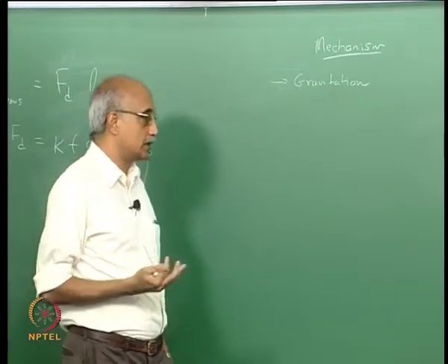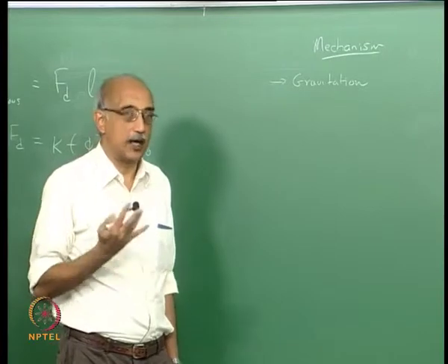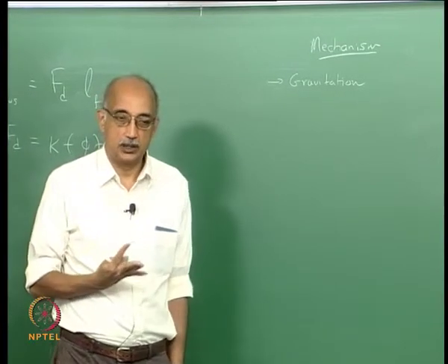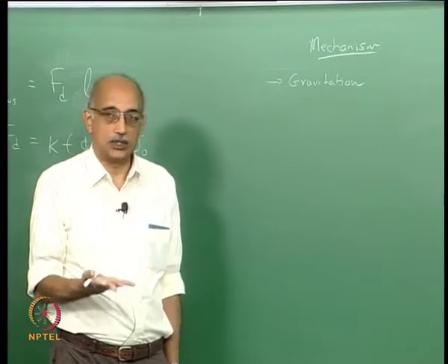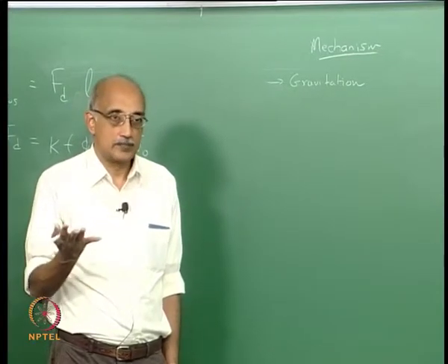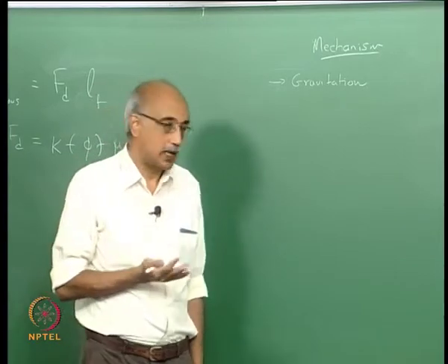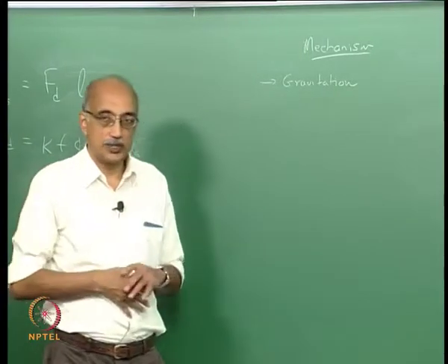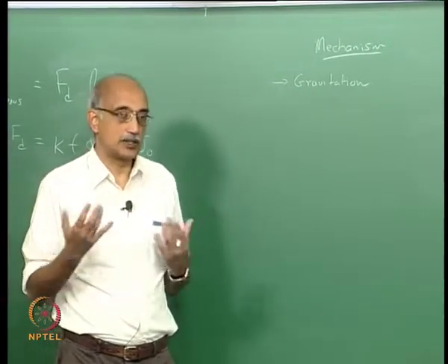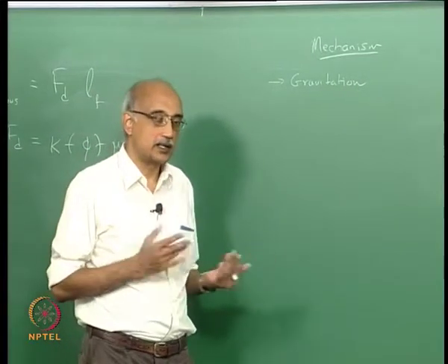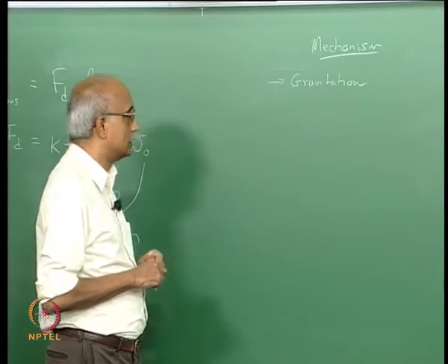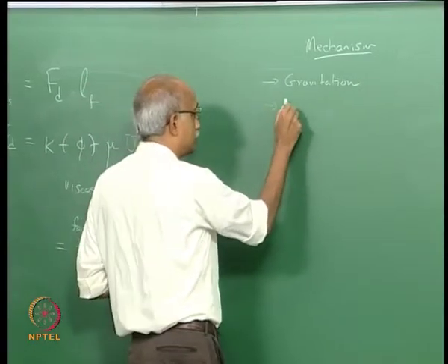So for example, the granular bed or the fabric filter that we talked about earlier essentially work by a gravitational mechanism. Particles simply settle into the filter media and get removed in that fashion, but that method is only valid for particles that are in the millimeter and larger size range. For particles smaller than that, gravitation is just not a large enough force. So the next one